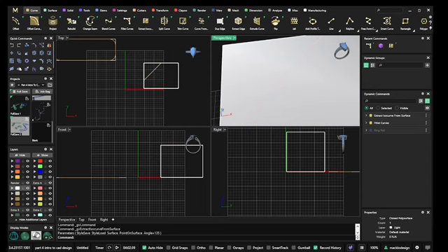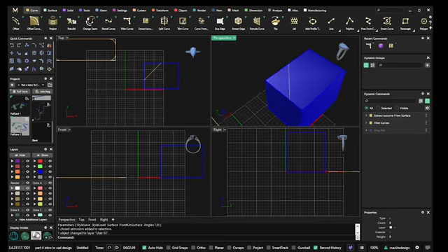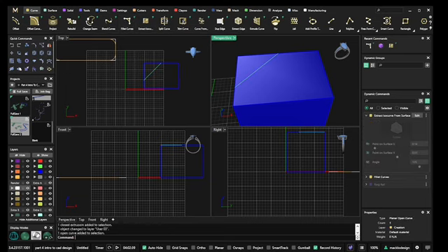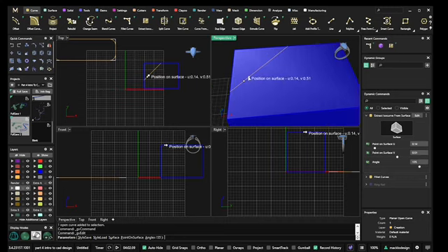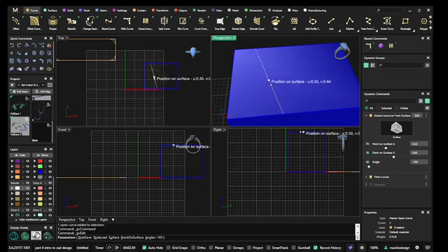There you go. Can you see that in the yellow? Change this color. There, I'll change it to blue so you can see it. There you go. And then it is a dynamic command. So if you clicked on this and highlighted your curve that you just extracted, you can come over here to your dynamic command box, and you can click on edit, and then you can adjust any of these things through the dynamic command box, or you could adjust it up here with the little wheel or the little dot.